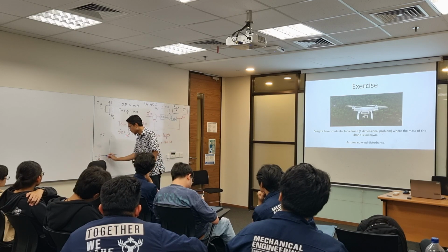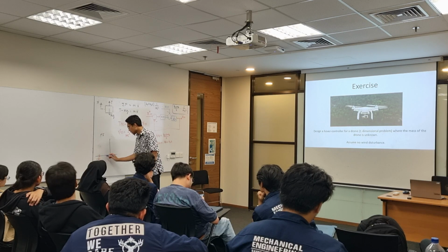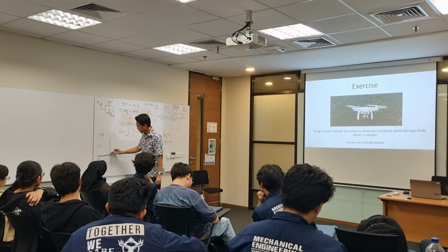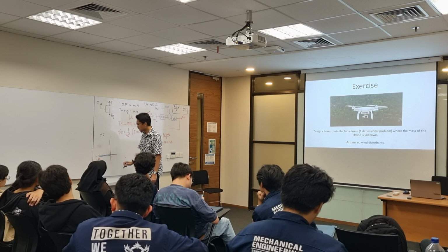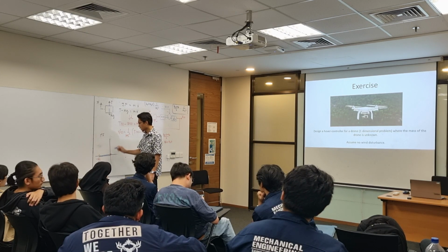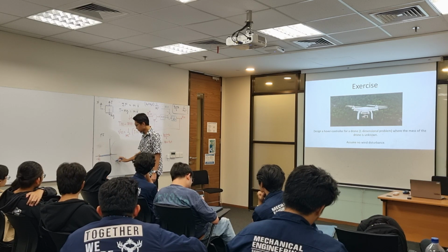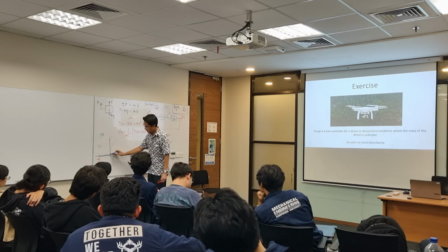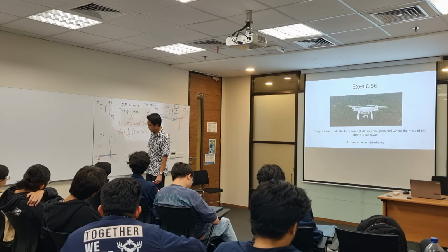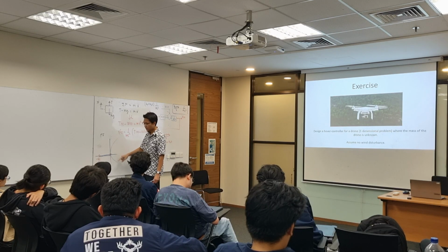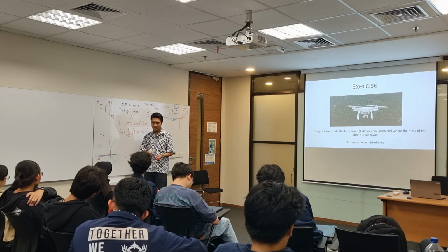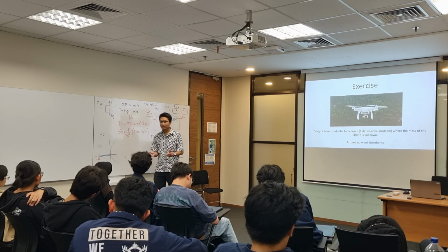There will be a root locus in here, and another one will be going there. So no matter what you do, your dominant pole will be unstable. PI control cannot work.